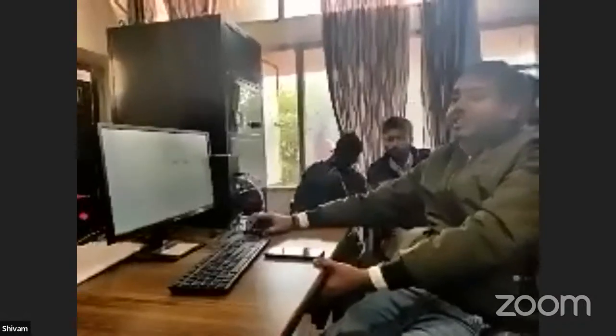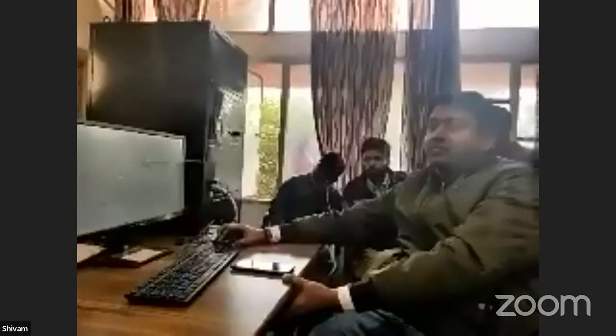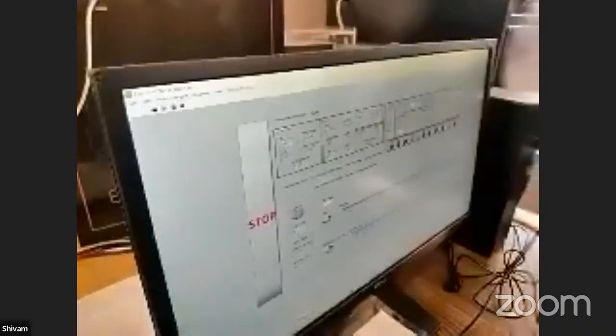I want to have a power electronic converter, so I can change its duty ratio from this. I can turn it on and turn the heat from this side. Whatever duty I set will be set from this point. I can also see the readings of my control here. Basically, it is a PMSG, so at the back end you have a DC motor. This armature voltage and this field voltage are for the DC generator. We are controlling the speed of the DC generator, and we are controlling the operation of the PMSG.